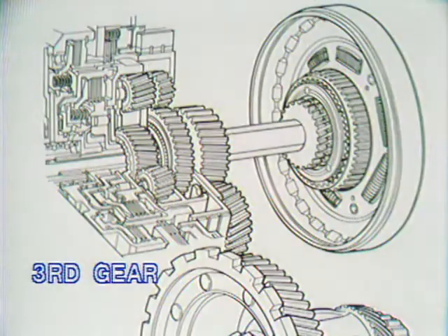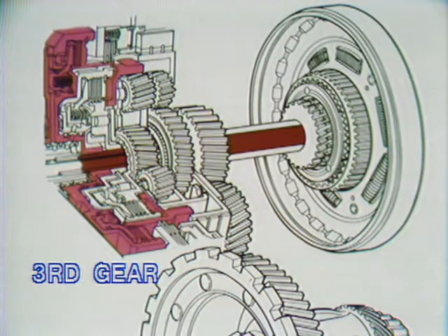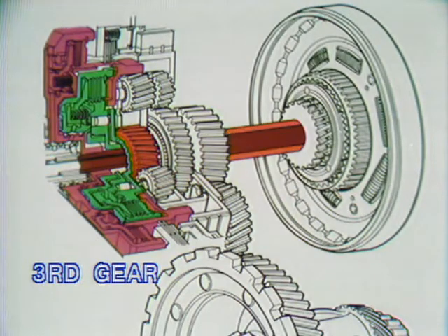Direct drive, or third gear, is our final exercise in ATX transaxle power flow. The chart shows that the direct clutch and the intermediate clutch are applied in third gear. Graphically, high gear looks like this. There is a split torque input through the intermediate shaft and clutch to the main ring gear. With the direct clutch on, the low reverse sun gear is locked to the turbine shaft and thus to the converter. This causes the main gear train to effectively lock up since two members are locked together through the converter. The planetary unit thus turns, in effect, at the same speed as the input shaft.